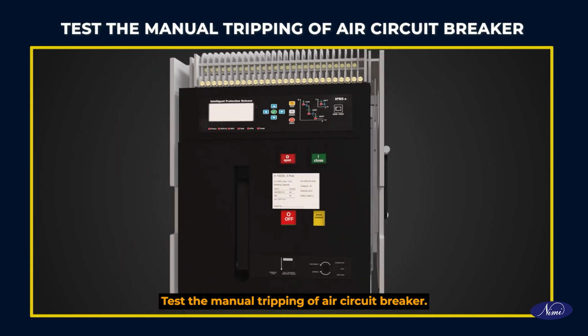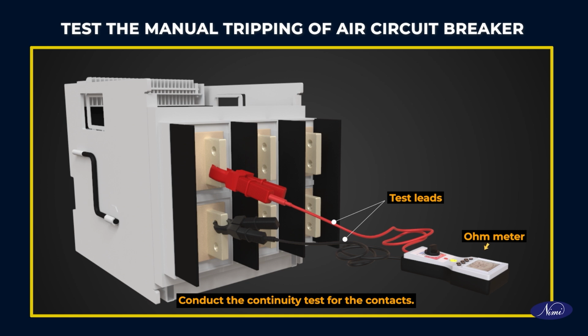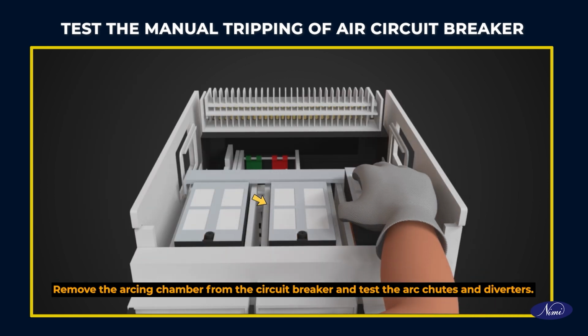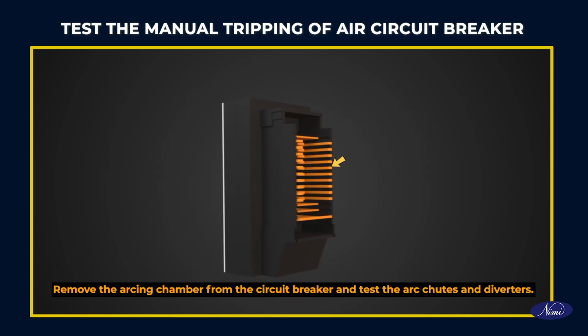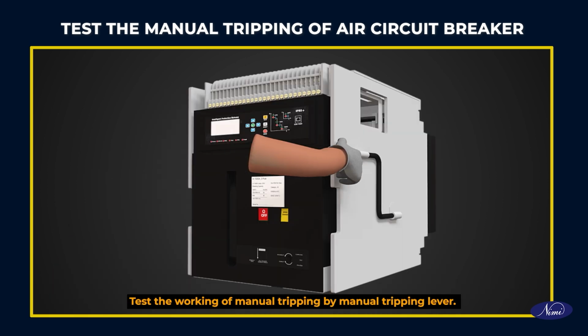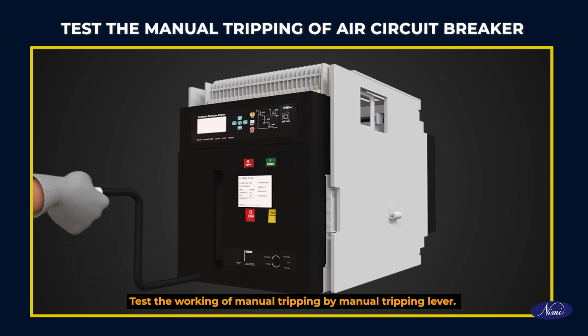Test the manual tripping of the air circuit breaker. Conduct the continuity test for the contacts. Remove the arcing chamber from the circuit breaker and test the arc chutes and diverters. Test the working of manual tripping by the manual tripping lever.